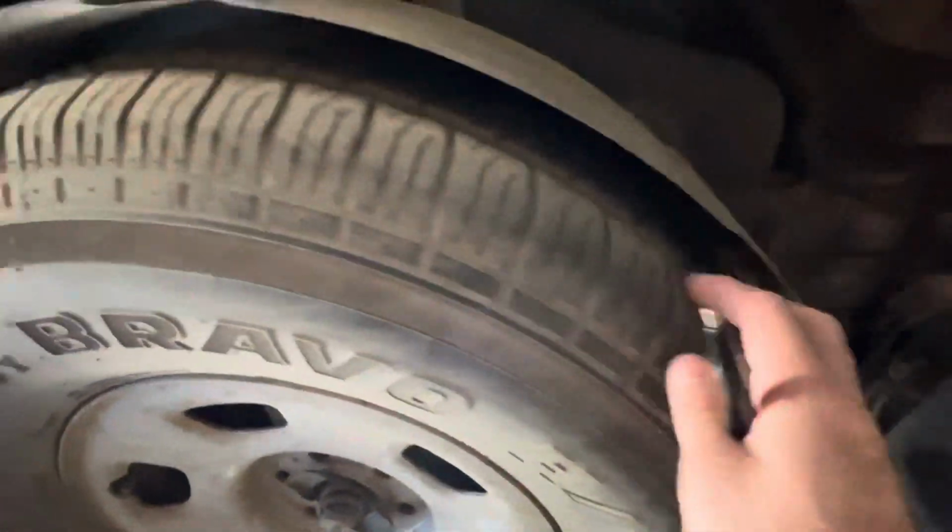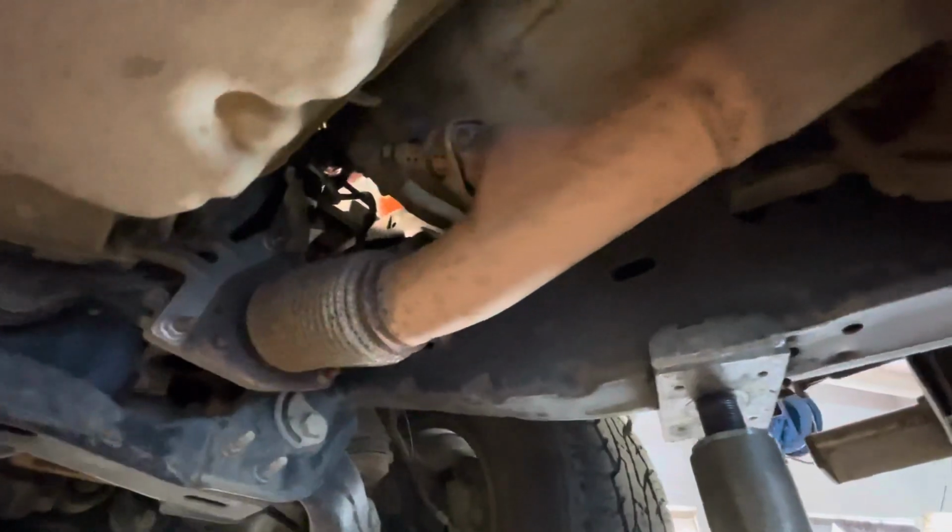I think that we probably have a faulty exhaust fluid pump back here. All this has to come down to do that. But they do want us to take the exhaust fluid injector out of the exhaust and just make sure that that's not dripping. So I may do that before I recommend a new pump.